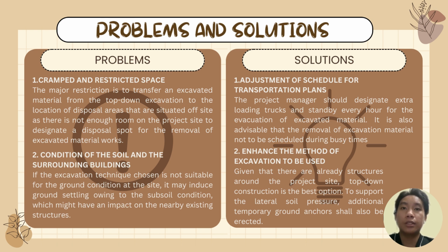Secondly, enhance the method of excavation to be used. Given that there are already structures around the project site, top-down construction is the best option. To support the lateral soil pressure, additional temporary ground anchors shall also be erected.